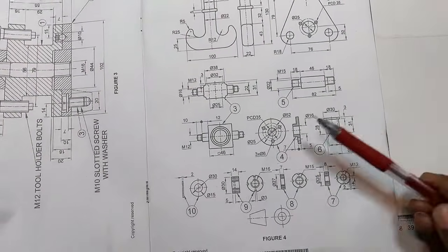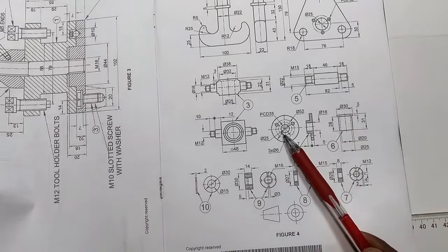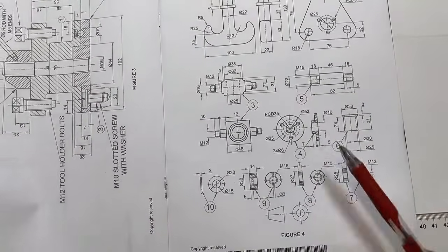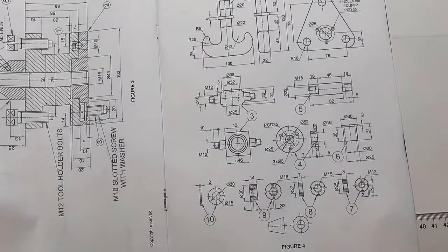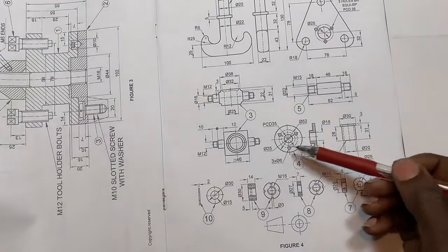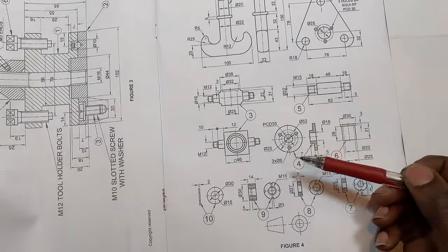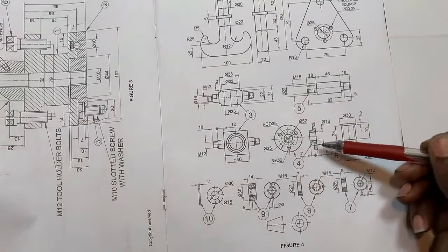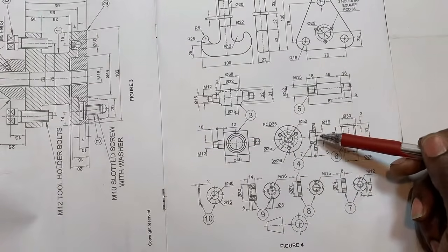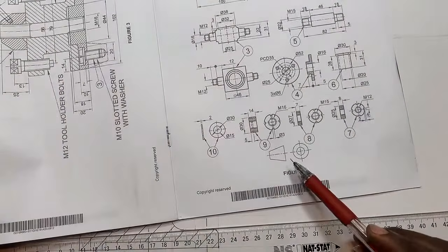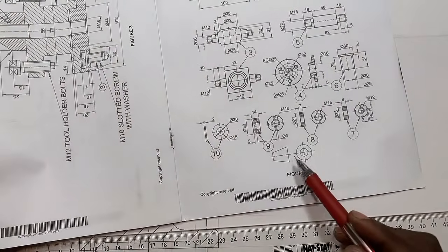Then this is going to be the front, this is going to be the left. When we draw, it will depend on whether we are fitting it using the front. But as far as I'm concerned, this one will be taking the left view. Remember, they are given in first angle orthographic projection.